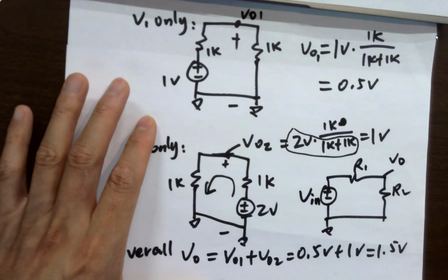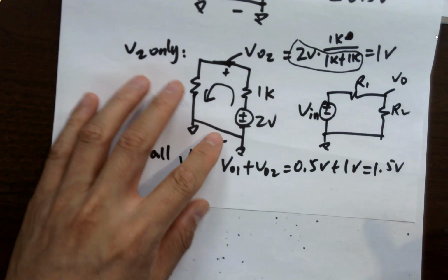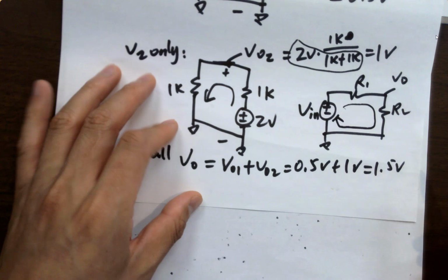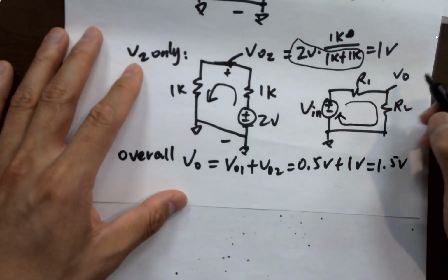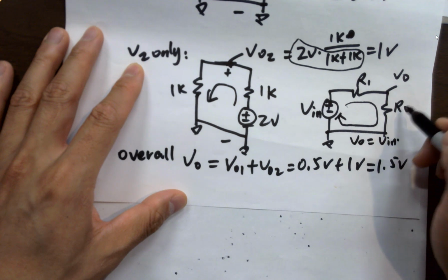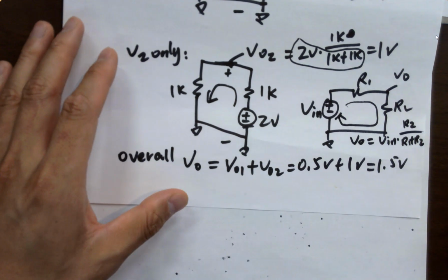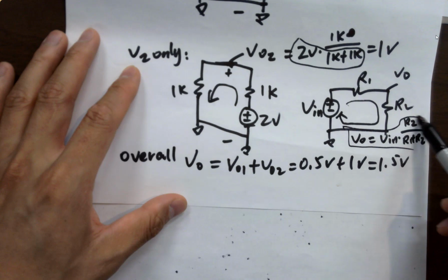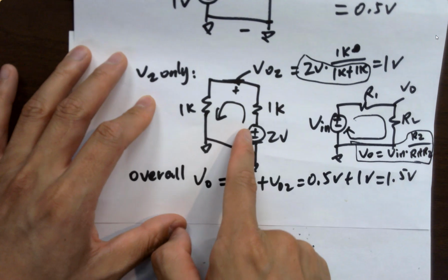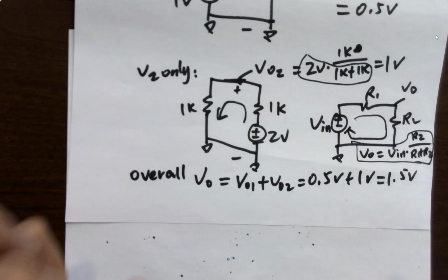Here's V out, like this. Apply voltage divider theory. What is V out? Same current. V out equals V in times this output resistor, which is R2, over R1 plus R2. Remember this. If you understand it, memorize it. In the future, just directly apply it. So see here, it's the same thing. You've got the 2 resistors, and this is the output node.